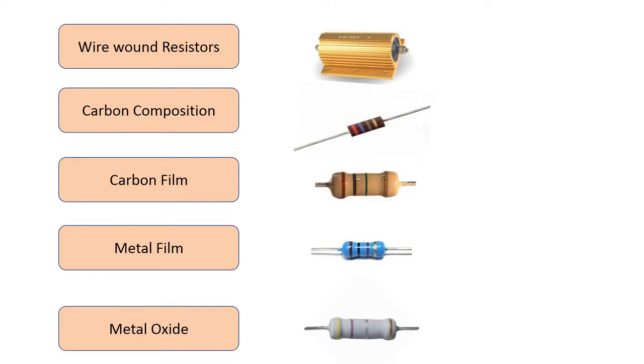The resistors can also be divided on the basis of the construction and the resistive material being used. Wire-wound resistors are the oldest type of resistors that were ever made and are still in use. They consist of a non-conducting core on which a resistive wire is wound. They usually have a very low resistance value, which results in a few advantages as well. They can have a fairly accurate value and are durable. But the disadvantage is the parasitic reactance which appears at higher frequencies.